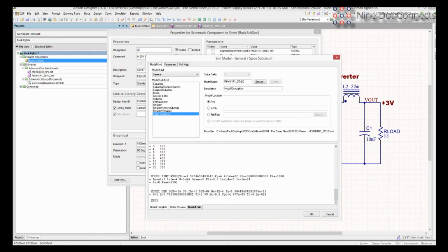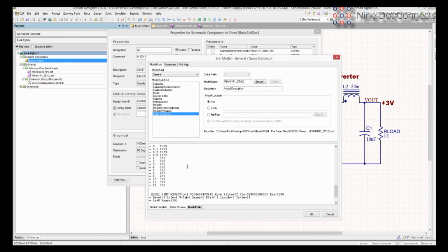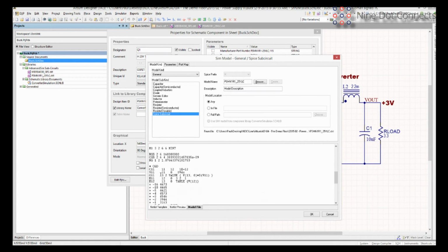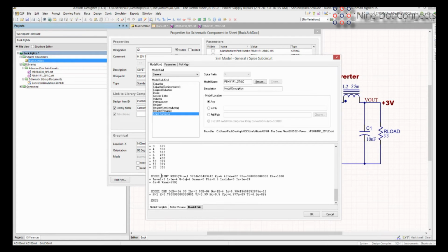have at the time. Well, I don't know if it was by mistake or coincidence or on purpose, but when Berkeley came out in the late 80s with an update, they not only did not take several of the things that PSPICE had, they basically created conflicts with certain elements. And again, what I mean by an element is what the first letter is over here, and I think in particular, it was the E element and the B element where PSPICE declares it one way and SPICE declares it another way. So as a result of that, you have a fork in the road, which has never really been fully reconciled.